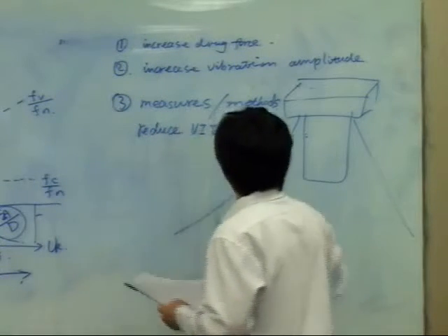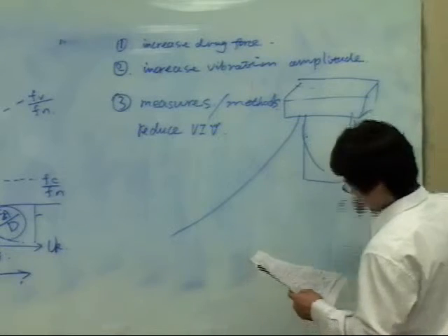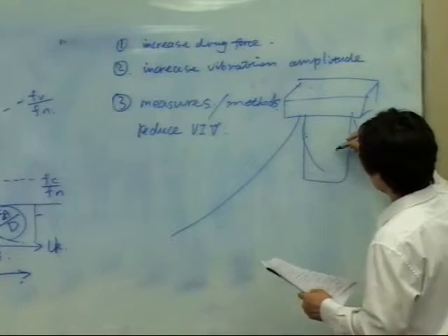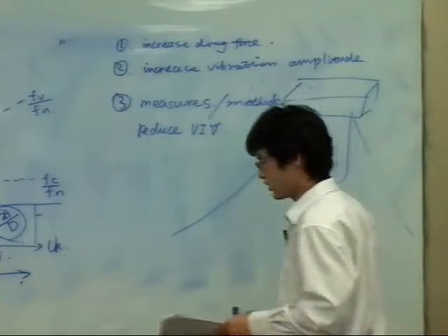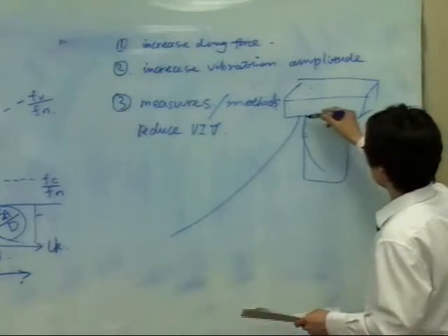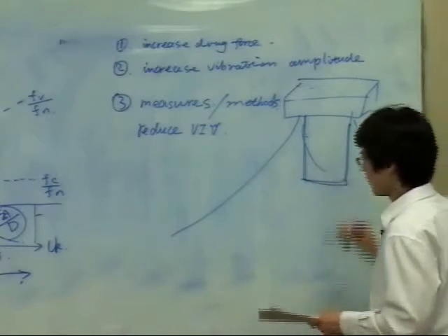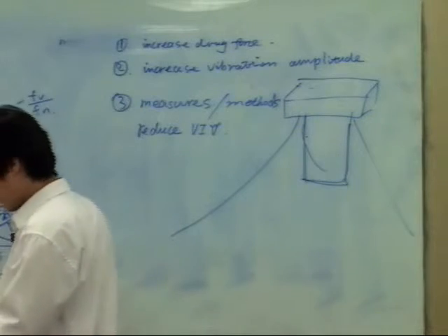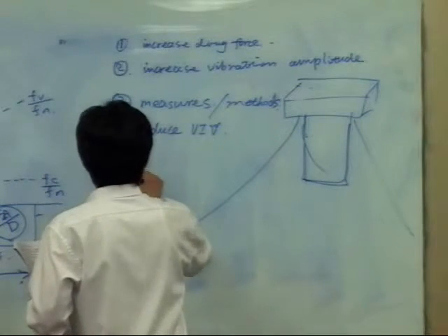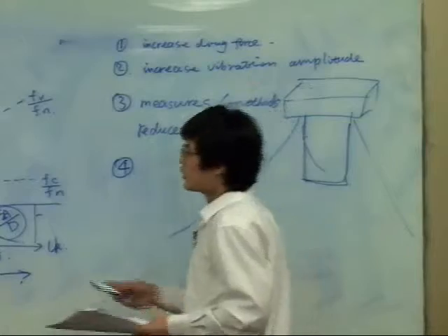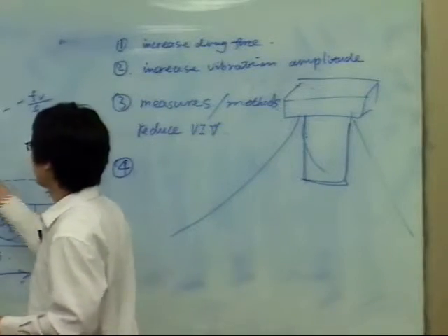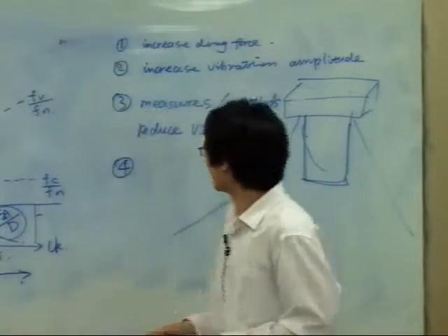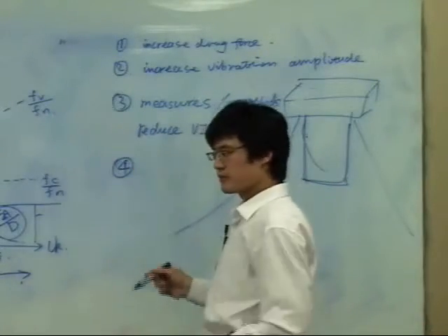One of the common methods is we put strakes, called helical strakes, around the hull of this offshore platform. I don't have a model. This can suppress the VIV. Some others use this phenomenon to actually increase VIV. Why do they want to increase the vibration?